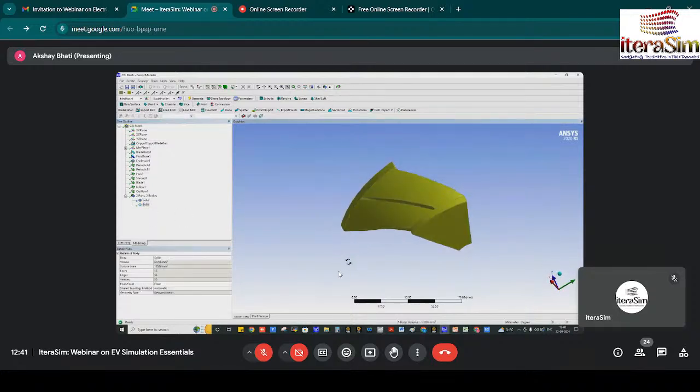So what is that fluid portion? All this yellow portion is the air, and the profile of the blade will work as a wall, like a cavity. So we can reduce the mesh count if we don't mesh the solid part, because from a CFD point of view, we don't want anything inside the material.